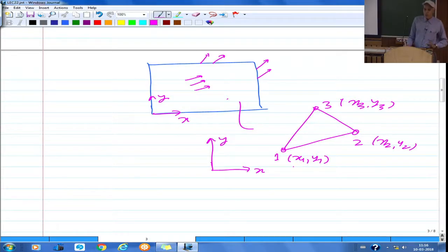So we will have only two non-zero displacements, and those displacements are basically displacements along the x and y directions. Let us say the displacement in this direction is u, and the displacement in this direction is v. u and v are going to be functions of x and y. That means some point which is originally here moves by a distance u along the x direction and a distance v along the y direction, and u and v are functions of x and y. So how will you go about formulating the element level governing equations for this? Is the question clear?